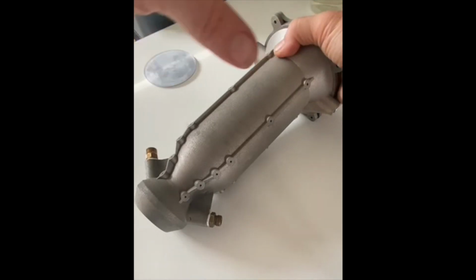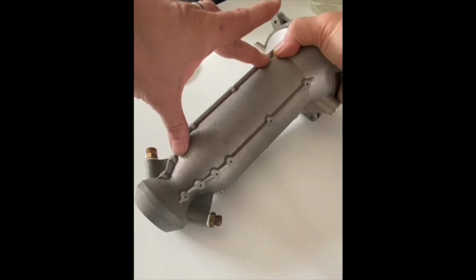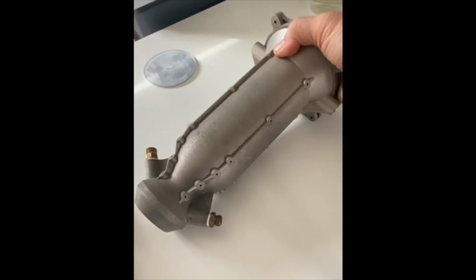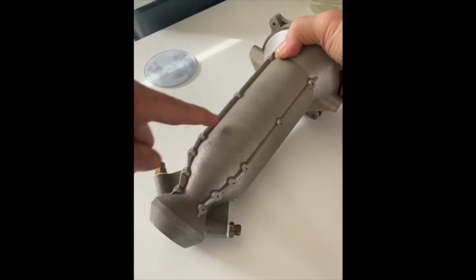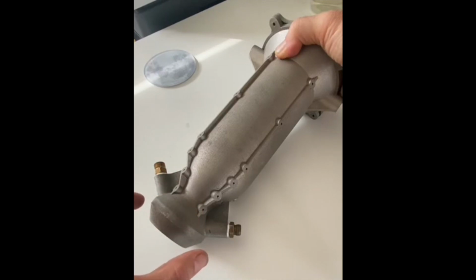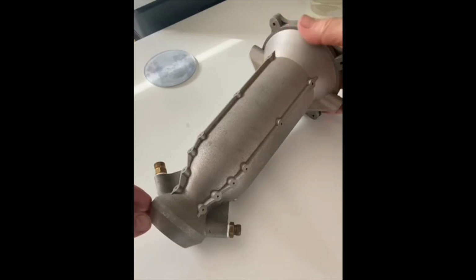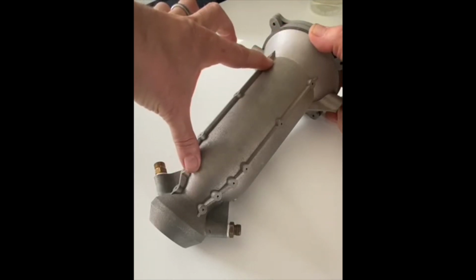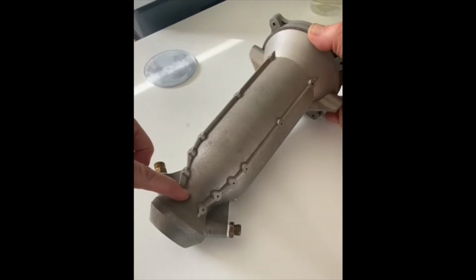The bulk of what we call the combustion chamber is actually the chamber part of it. So it's an area inside here where combustion is designed to go on smoothly to liberate chemical energy from the propellants. Then you have a throat here where the chamber tapers to the narrowest part, a little bit harder to see here, and then it expands into what's called an expansion cone to allow acceleration of the gases to maximum velocity. So we have injector, chamber, throat, and then finally nozzle.